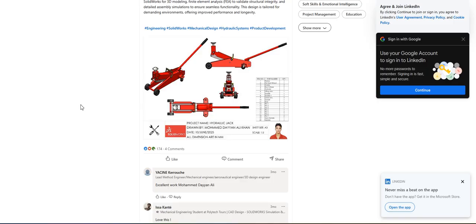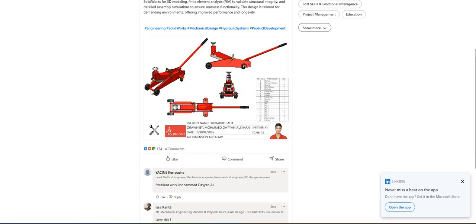I think we explained the side plate and the sand casting process. Most of the parts are going to be pre-cut and joined together by the welding process. There is actually no other way to make the trolley jack except by casting and plate cutting by the shear cutting operation.